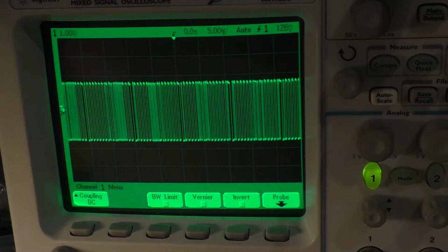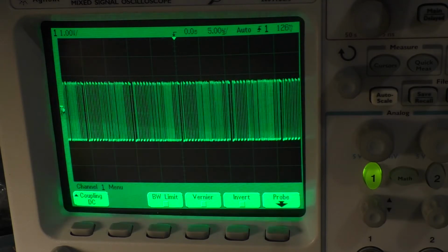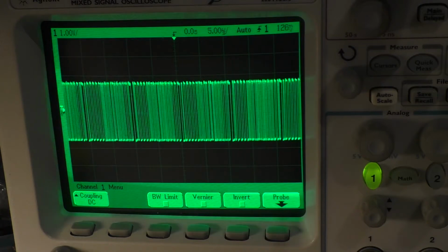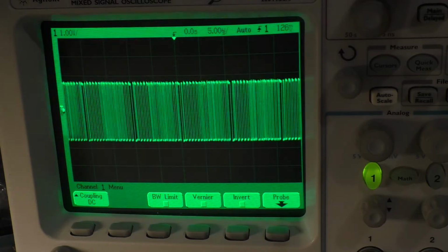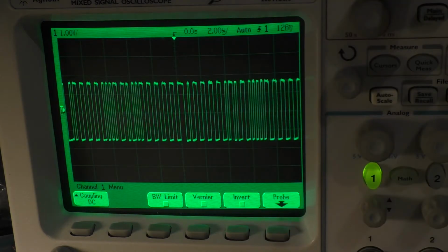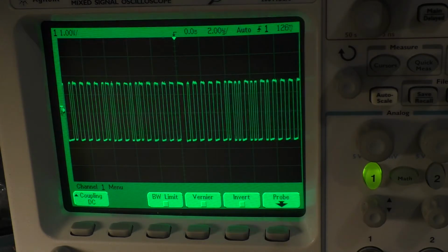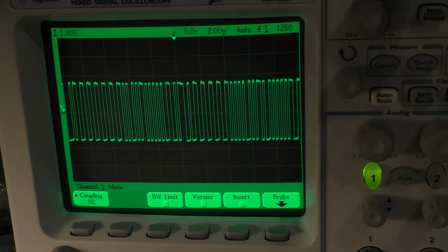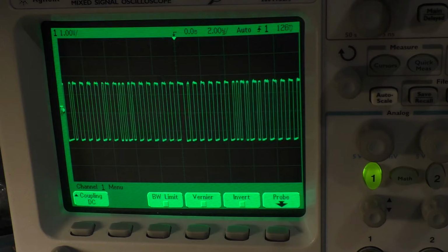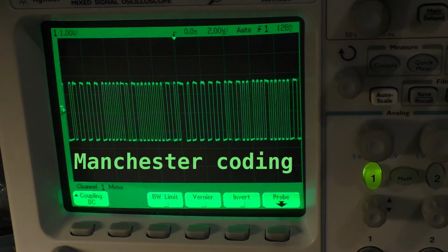The first signal in the headphone jack path is SPDIF. So this is how SPDIF looks on an oscilloscope, and if you are not familiar with what coding scheme this is, it basically looks like two square waves, right? A square wave with some frequency and then seemingly at random interleaved a square wave with another frequency, which is twice the frequency of the first square wave. And this is so-called Manchester coding.